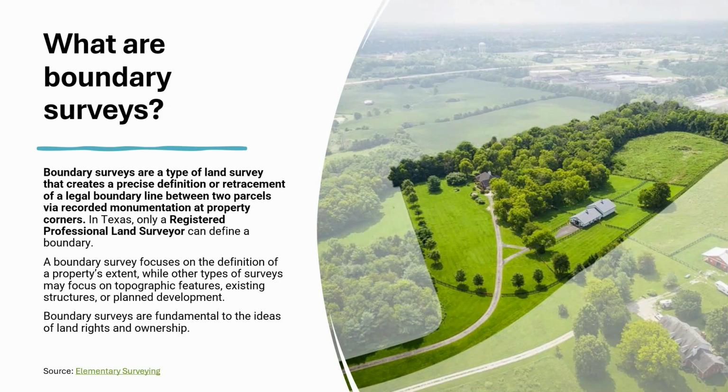Getting back to the focus of what boundary surveys are: they're surveys that explicitly focus on defining a property's extent, or its footprint, in this world, particularly in relation to its adjoiners. And then there are other types of surveys where a boundary may be included, but it's not necessarily necessary. Things like topographic surveys, like if you're out flying a drone to collect continuous topographic information, extent is not the same thing as a boundary. A boundary is that legal definition.